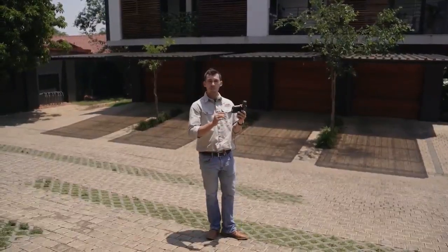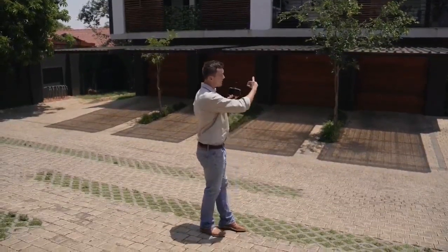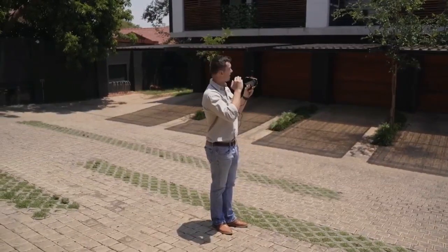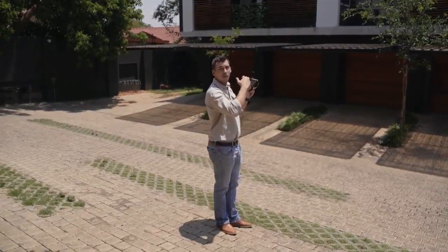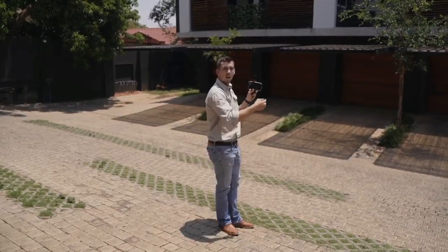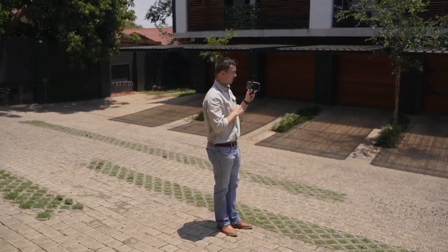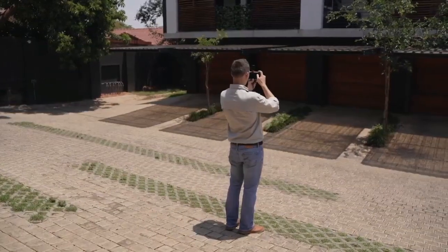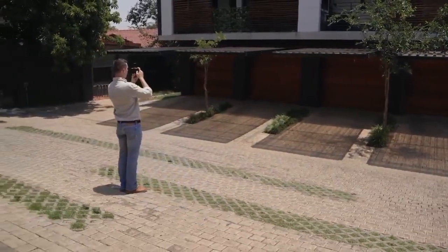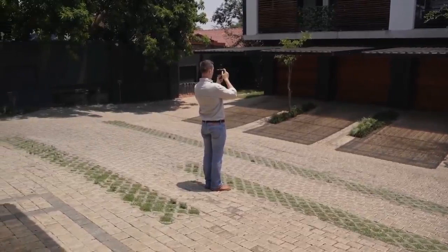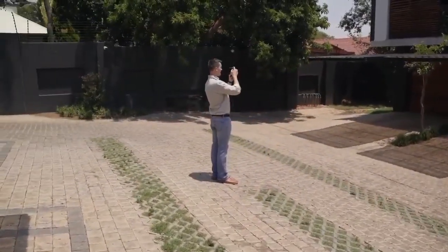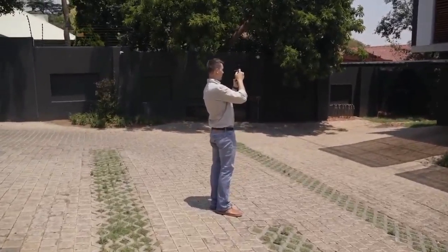Great, so to create the best possible model, I've identified a distance that I need to be from the building, which will be able to accurately get all the data, the full spectrum and size of the building. I will continue and maintain that exact line until the end of my survey. I'll also make use of equal steps to make sure that my data overlap is correct and maintains a 70% overlap.